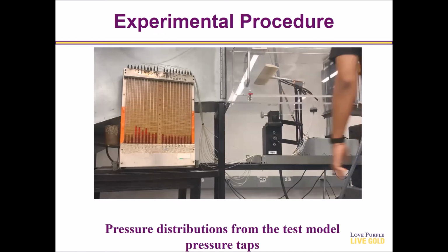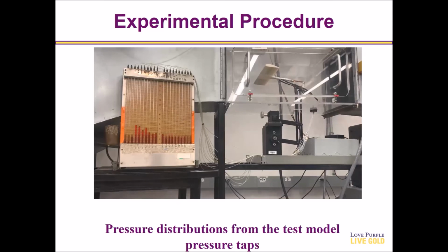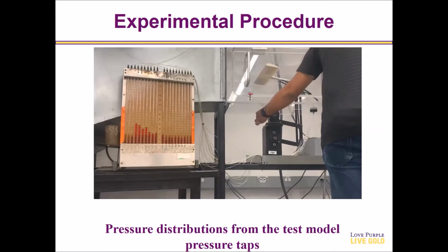However, as the angle of attack is increased beyond 15 degrees or so, at a particular angle of attack you will notice the top airfoil surface pressure significantly increases. The initial angle at which this trend of pressure increase starts is identified as the stall angle.